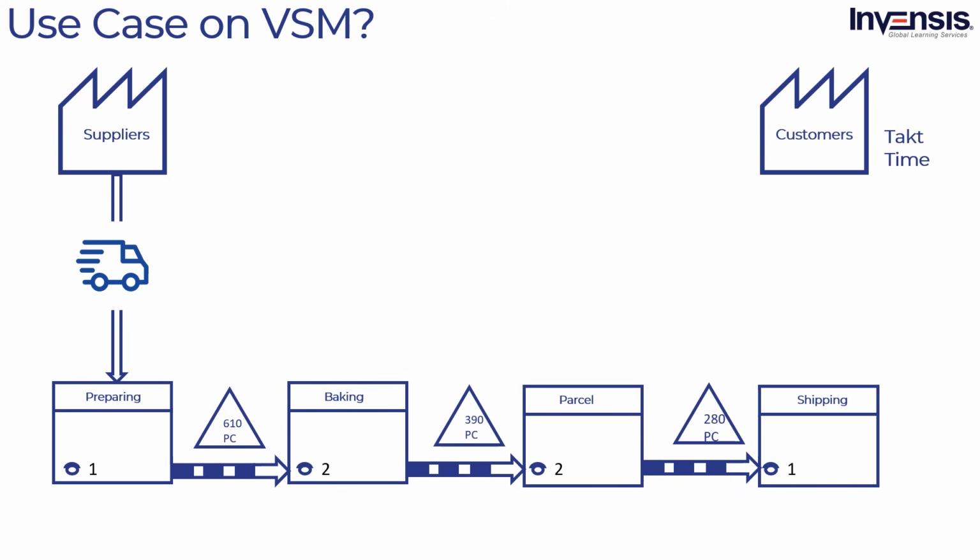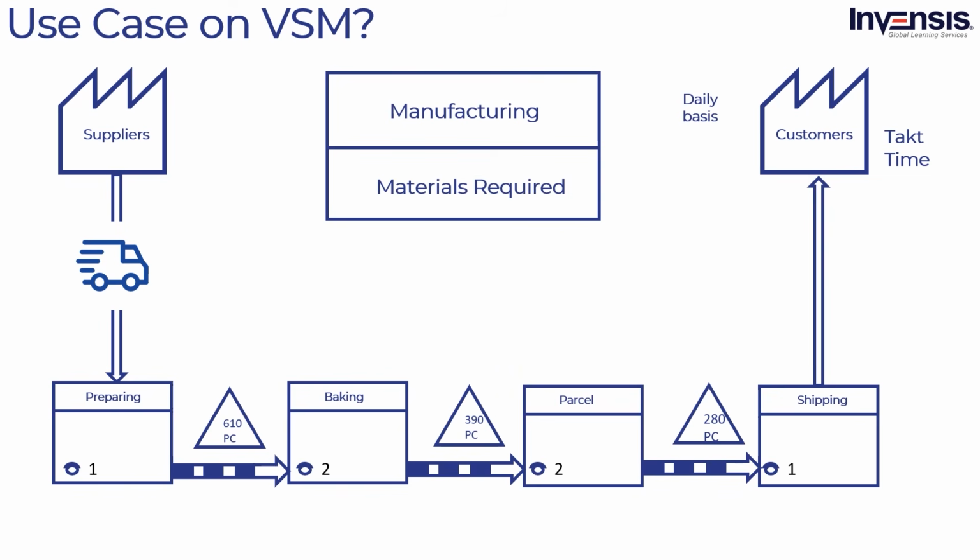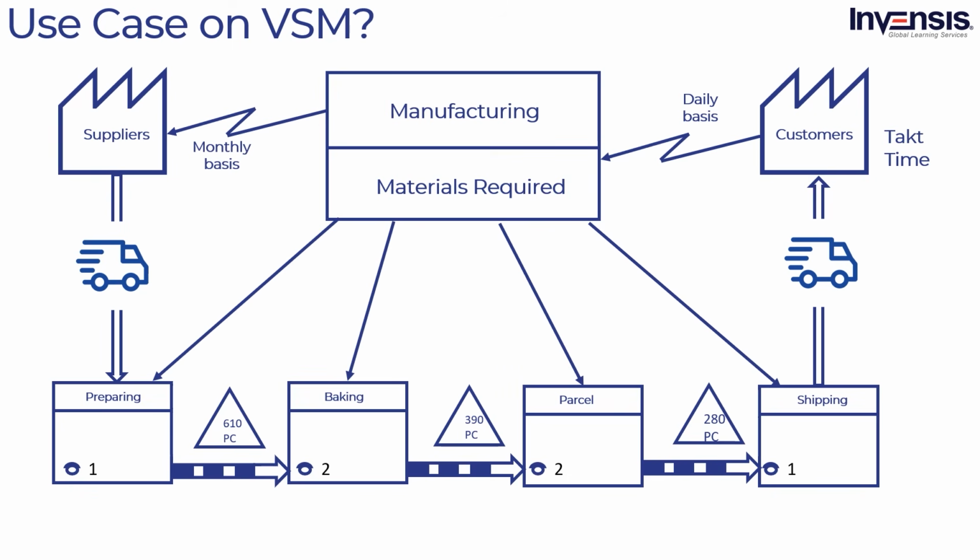Now, in between each process stage, add inventory to mark the number of parts you have in work in progress at the end of each step. Also, include shipments. After this, add a production control box to represent the scheduling and controlling of production. You can add this group's responsibilities in the same box. Then add communication lines. In our example, we receive orders from the customer on a daily basis and send weekly forecasts to the supplier electronically, but they give daily schedules to the production staff in person.